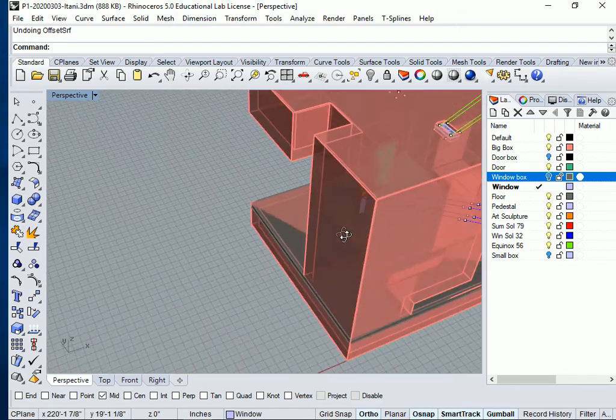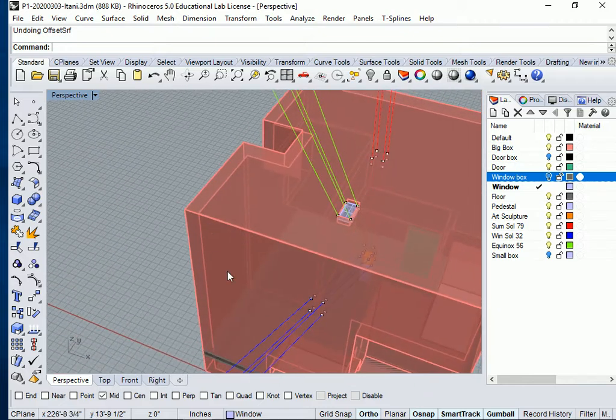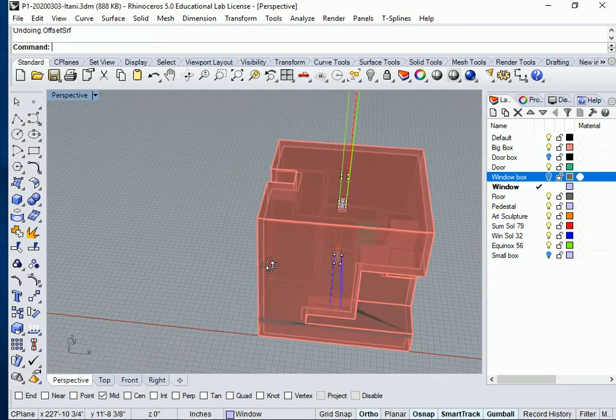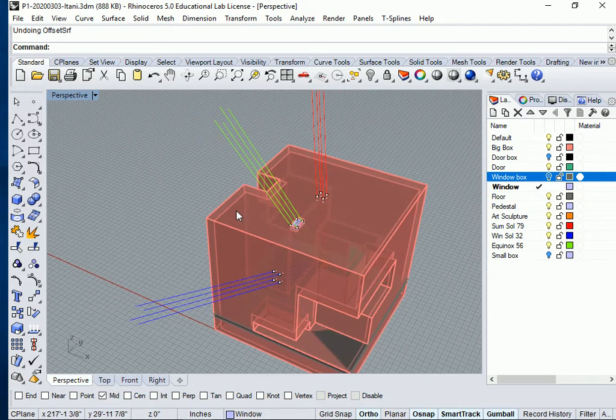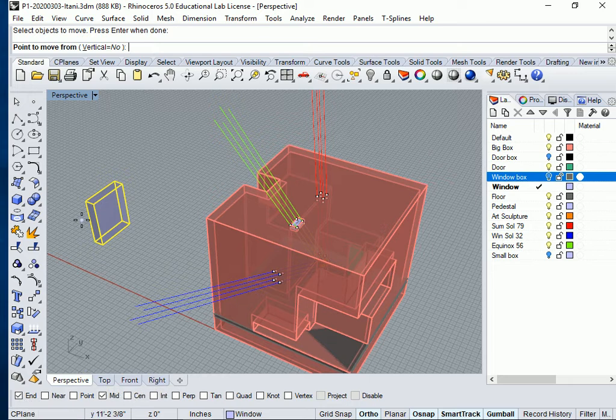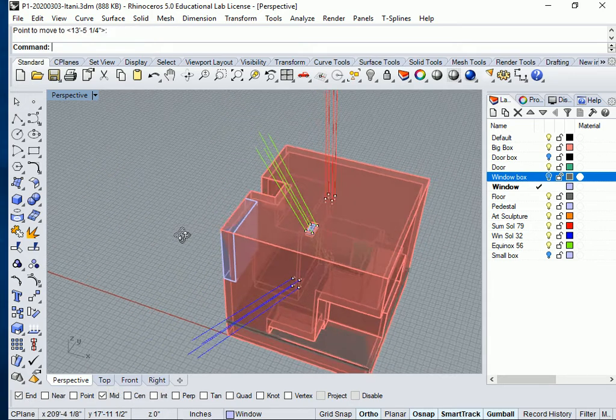If you're in Iggy's class or in Hero's class and you guys are going to do a lot of windows, you're going to do a lot of other windows on your project, and you may end up with a window on a corner. I'll teach you how to do that as well. If you want to put a window here, you can simply do a box like so, however tall it is, which would be your opening, and then you grab that box from endpoint to endpoint, okay?